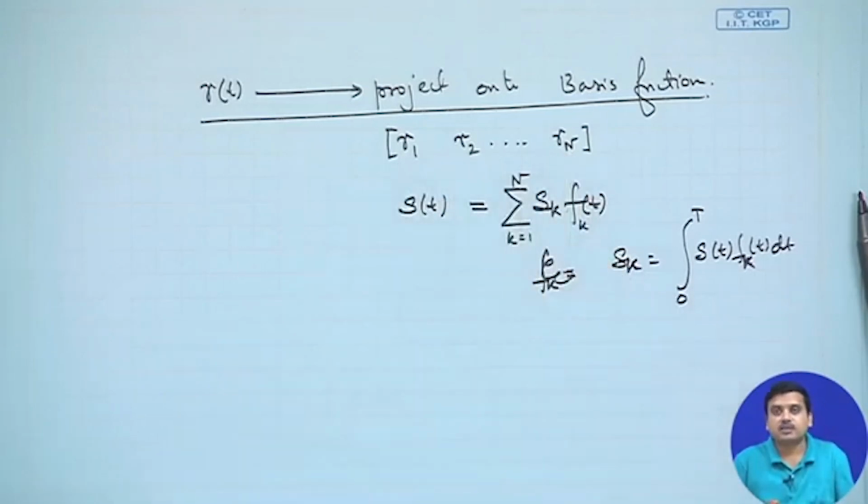When we discussed M-ary FSK, we did say we are calculating the cross correlation function. When calculating the cross correlation function, we integrated the received signal multiplied by any one of the other signals, and the complex conjugate of it. We wanted to establish that the received signal is orthogonal to all other signals than the particular component on which it has been sent.